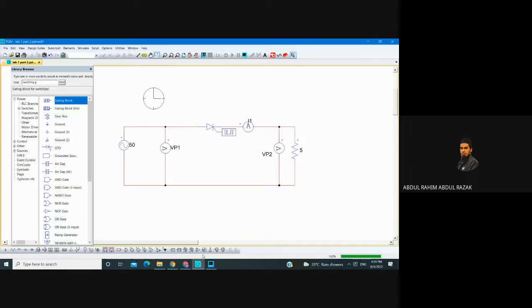Okay, when we involve a processor in between our load and source, we assume that our simple diode thyristor and the gating is the system or the converter. So we have to present the source signal as well in the simulation result. So you have to put one floating voltmeter, a volt probe, on the gate. Put it at the gate, then simulate again.